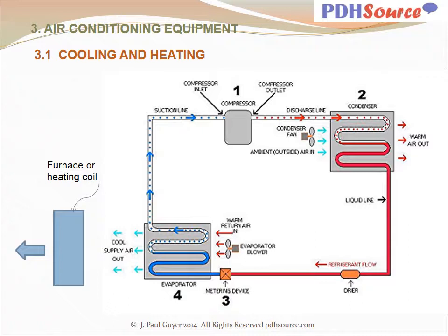Typically, the way that air is heated is through a heat exchanger, which can be like a box, and you can have an external flame that is heating the box and making it hot, and then you would have an internal structure, fins and things like that, to control and slow down the passage of air.